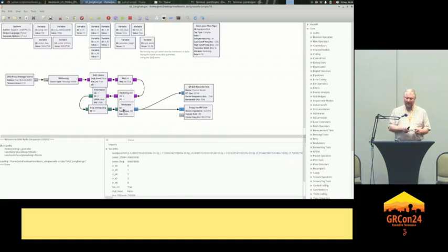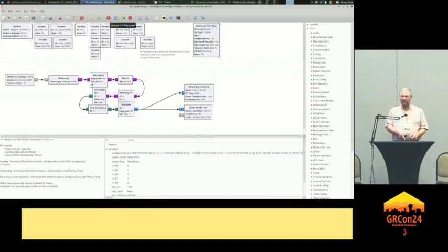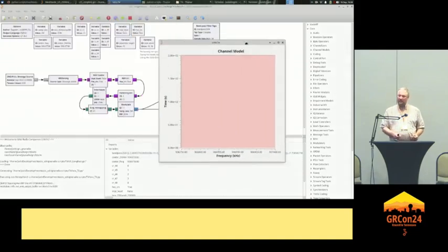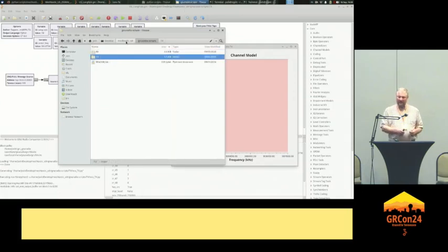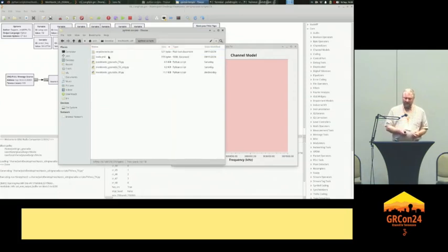In this case, what we're implementing is the long fast, which I believe is SF12CR4, frequency 906.875, bandwidth of 250 kilohertz. And again, this opens up a port for 0MQ, except it's not 20,004, it's 30,004. So again, it's simple, you send bytes into it, and it transmits it out only. And we can demonstrate that.